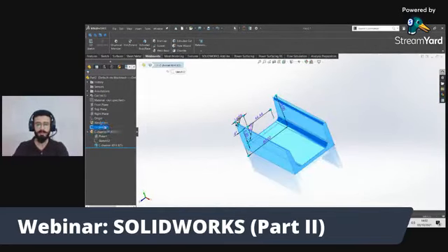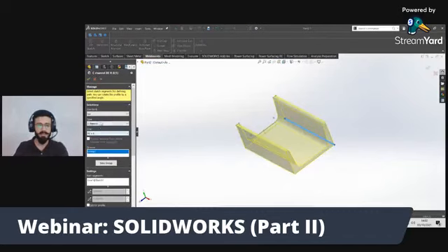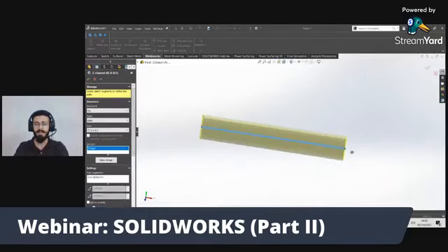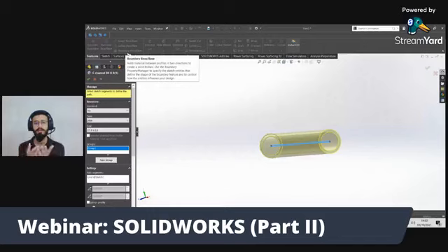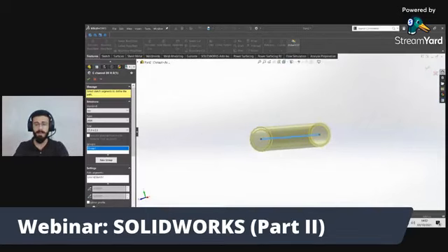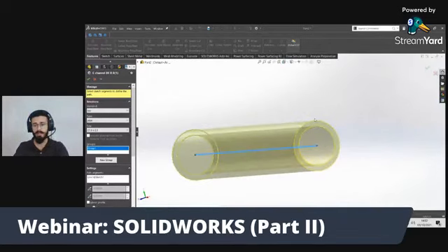And the third option given by SolidWorks is a pipe. It's just a basic circular pipe. We can also design this through features, as I mentioned to you yesterday. There is an option, swept boss base. Through this option we can create this. First we have to use swept boss base, then we have to use the shell option to create this pipe. But in that case, we have to decide the inner dimension, outer dimension, all things by ourselves. We can make a mistake.